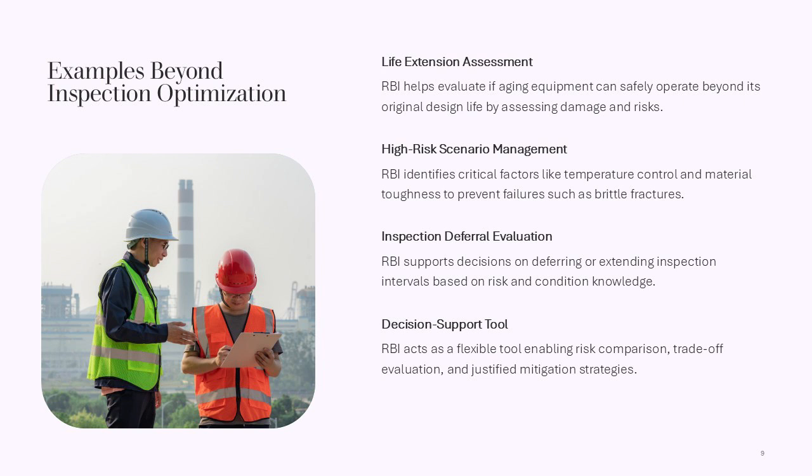Another example is the evaluation of inspection deferrals or interval extensions. RBI provides a technical basis for assessing whether deferring an inspection will result in an acceptable level of risk, considering current condition knowledge and degradation rates. This capability is particularly valuable during turnaround planning or resource constraints.